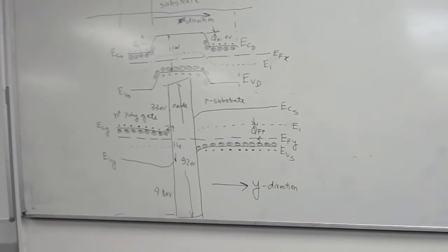So between the gate and source, I am going to apply voltage VGS, which is, as we said, greater than threshold voltage, greater than VTHN. And the body and the source will connect together. We will not have any body effect. If you make this connection, how much is VSB? Zero, isn't it? VSB is 0. So all of this together can be connected to ground.